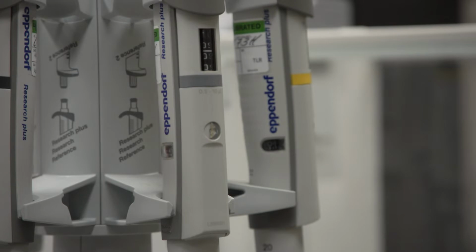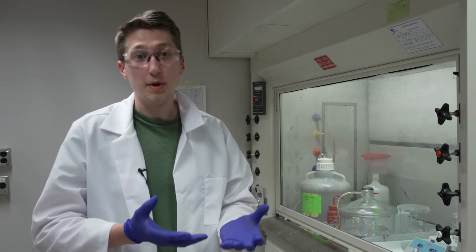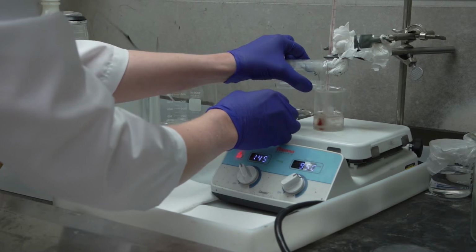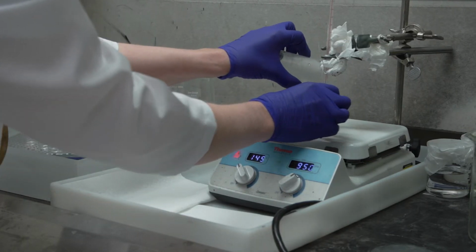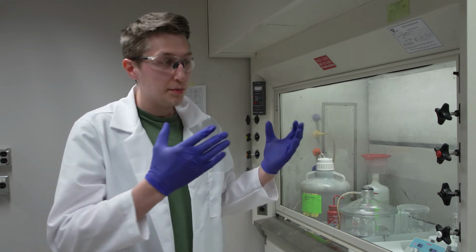My research focuses first on the synthesis, stabilization, and functionalization of silver nanoparticles with groups that are favorable for CO2 separation. These nanoparticles will be incorporated into a polymer membrane for gas separation, which would be useful in the natural gas industry or other industries. Current separation techniques, such as distillation, can be quite expensive and very energy intensive. So the purpose of materials science is developing new materials that we can incorporate into membranes to produce a more energy efficient process.